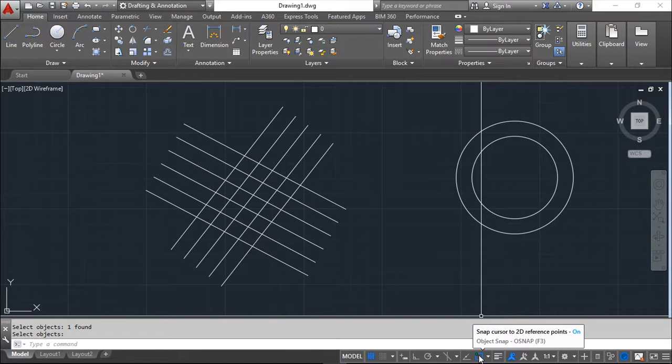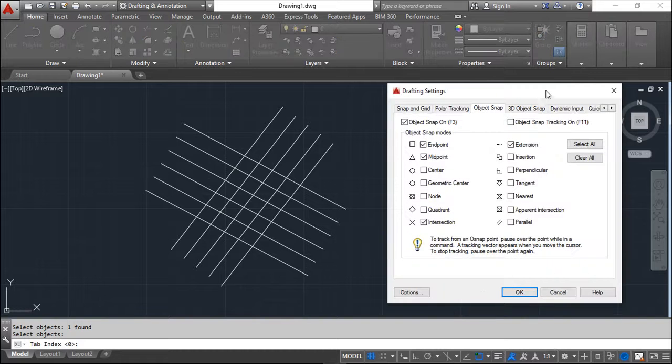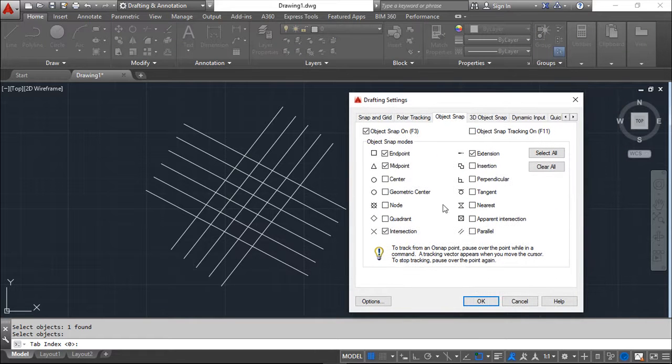this icon here, that we can call, and if we click with the right mouse button, we open the object snap settings, and I open this window here. And I have several types of snap modes, object snap modes, and whatever I put here is permanently chosen. So let us see an example. I will leave only the endpoint.